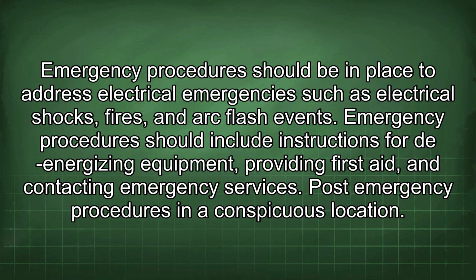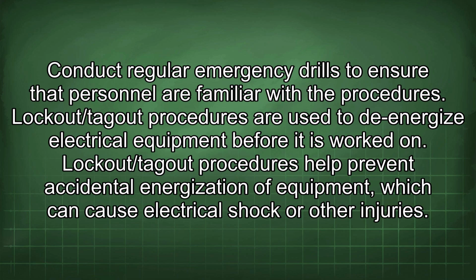Emergency procedures should be in place to address electrical emergencies such as electrical shocks, fires, and arc flash events. Emergency procedures should include instructions for de-energizing equipment, providing first aid, and contacting emergency services. Post emergency procedures in a conspicuous location. Conduct regular emergency drills to ensure that personnel are familiar with the procedures.